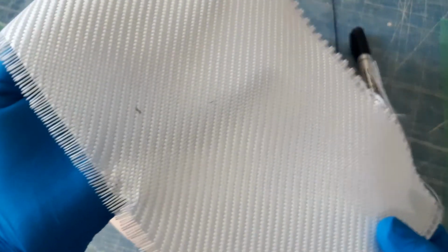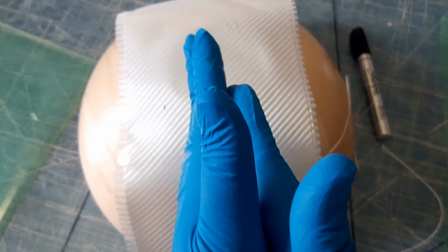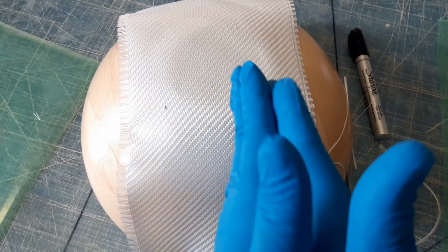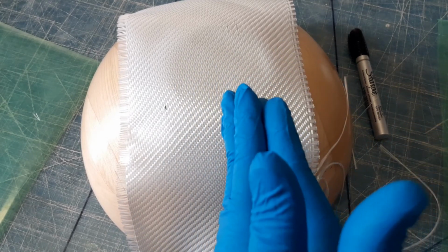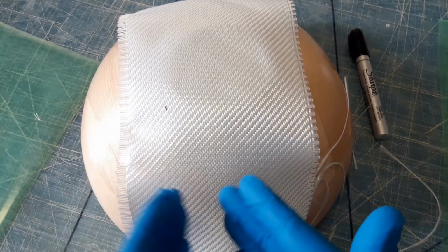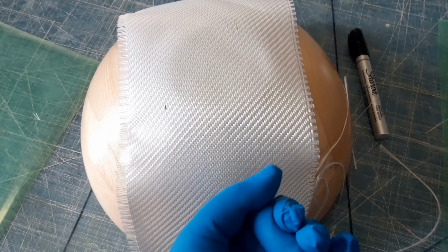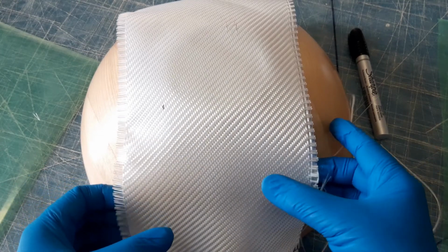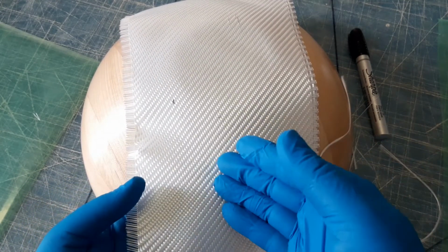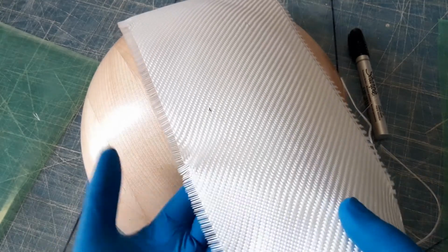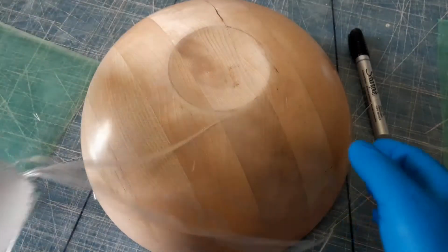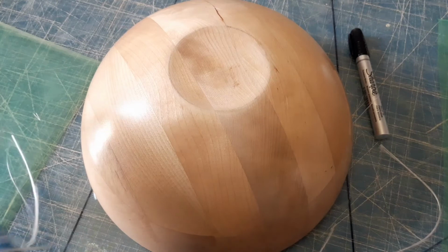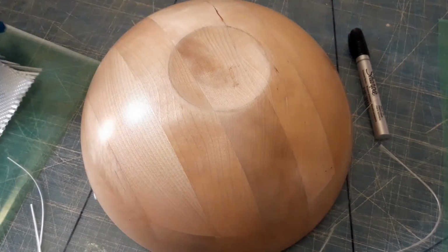Of course, this is a slightly thicker material, and the reason it does that is because there is a certain ability of these fibers to slide among themselves, because there is no epoxy or any matrix in the middle that is preventing it from sliding and from transferring the loads from one fiber to the other. There is nothing there. So that is the reason why it is free to slide, and it does so and takes the space of everything.